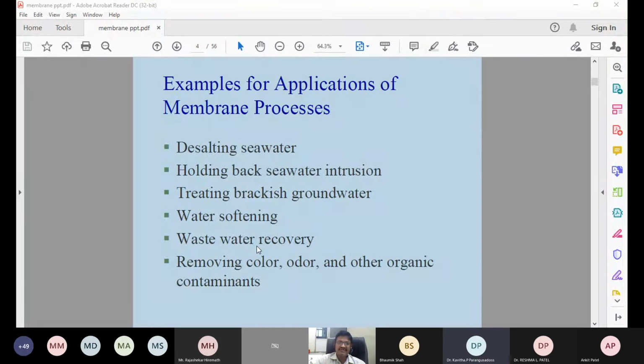You know, the deeper your borewell, from where you are taking the water, the more TDS it will have. Therefore, sometimes where water scarcity is there, if the borewell is very deep and you take the water, it is not drinkable, because its TDS is generally in the range of 2000 to 3000 milligrams per liter, which is not a drinkable form. Okay.